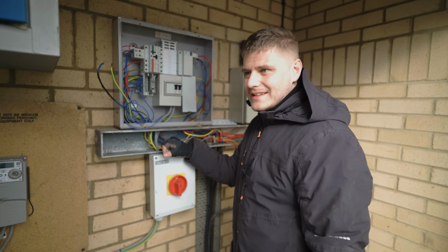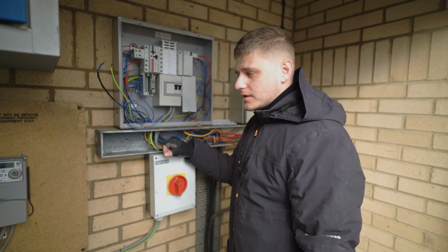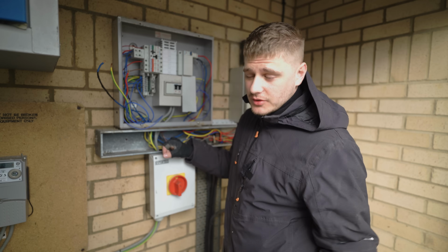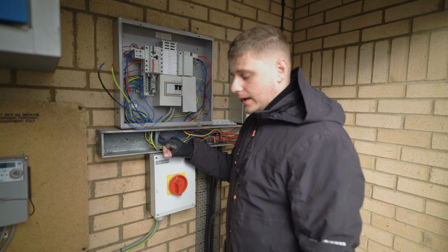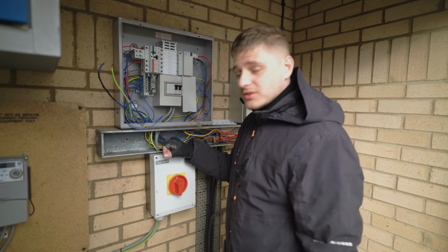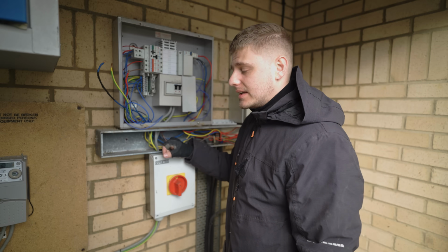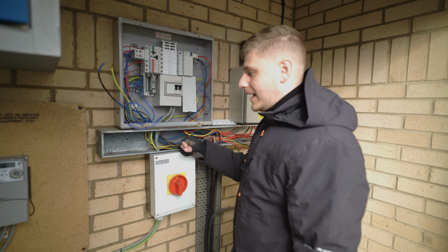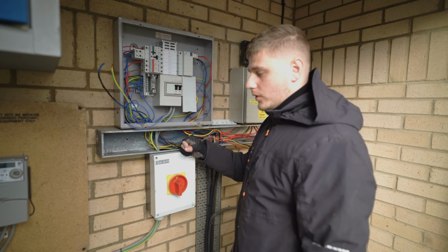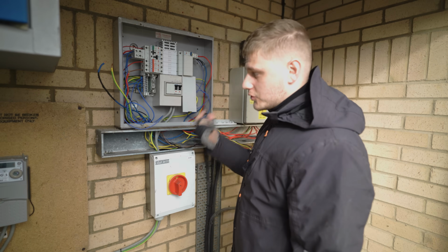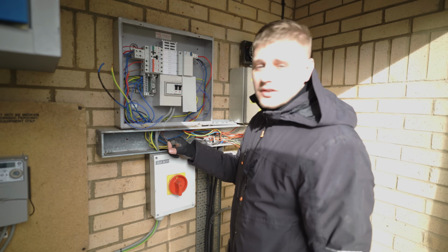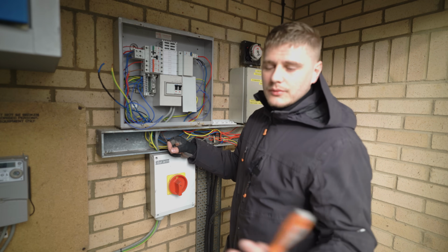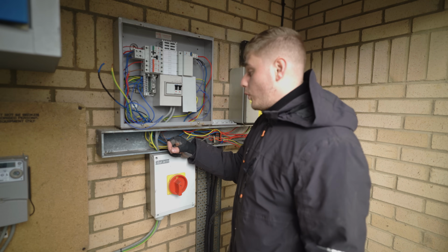If you don't know what that is, it's basically ingress protection. There's loads on it in the regs. The IP stands for ingress protection, obviously. The 4 is for access from solid objects or persons, and basically anything bigger than 1mm shouldn't be able to get in. And then the X after the 4 is for the ingress of water, which obviously trunking has no protection against, so you just have an X instead of, you know, IP67 or 47 or whatever. So that's what IP4X is.